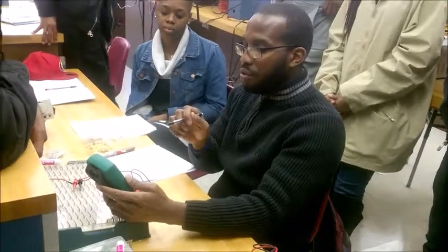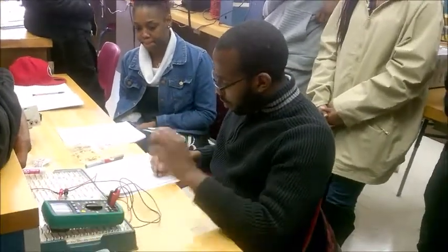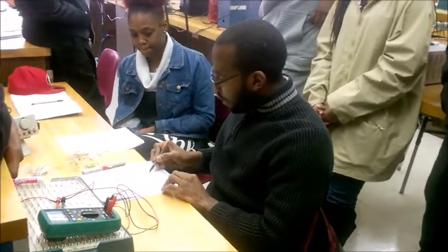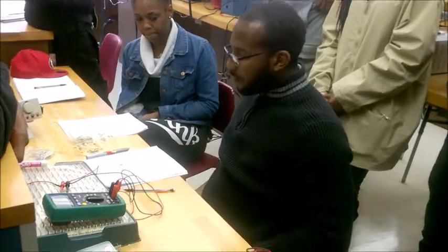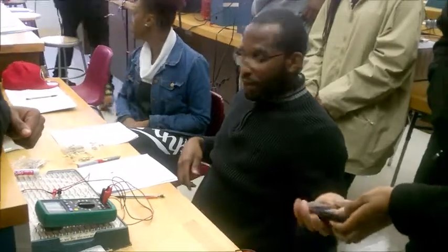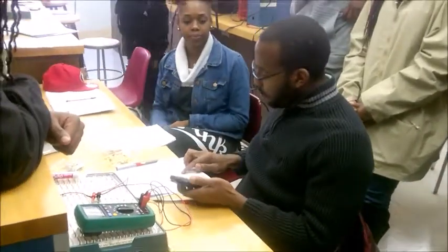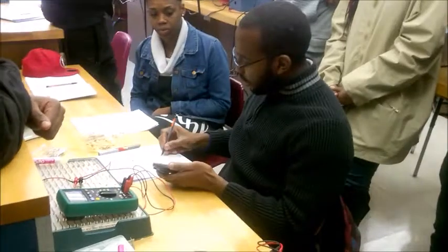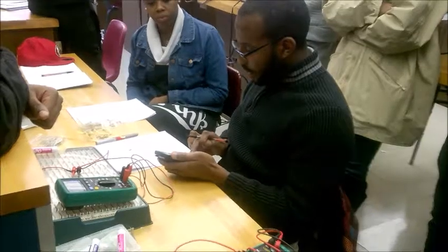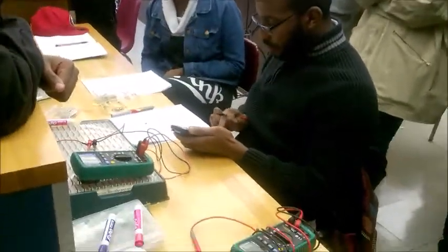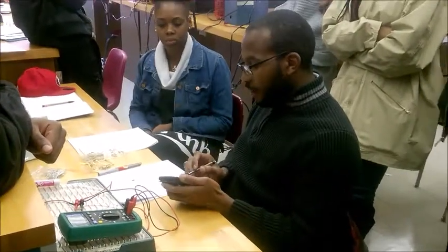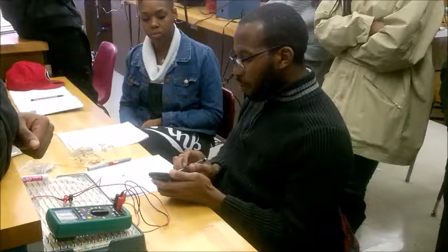And so we have 325.5 ohms. So I'm going to write it down here. 325.5 ohms. Now, to get my current, I just need to divide. So, anyone's calculator? Okay, never mind. So, in this case here, to find the current, it is going to be the voltage divided by the resistance. So 1.009 divided by 325.58. Okay, so I have 0.00309. So this is the same as 3.09 milliamps.